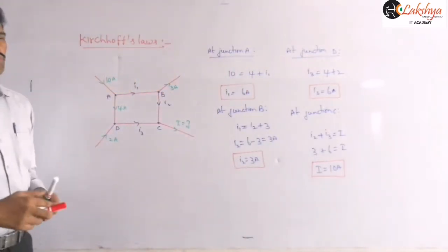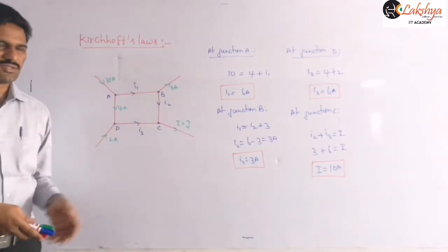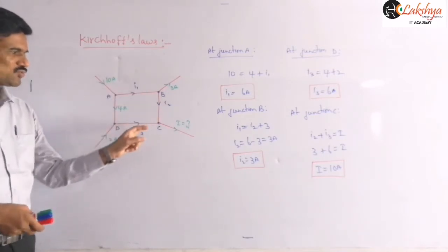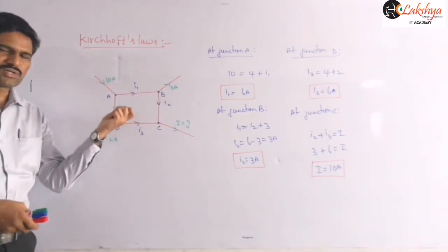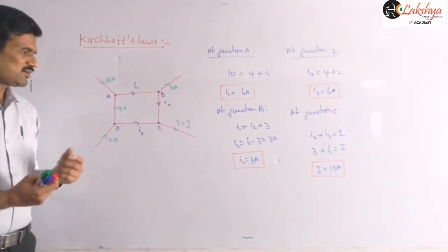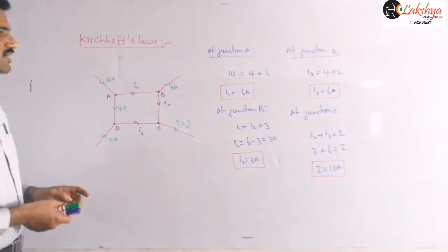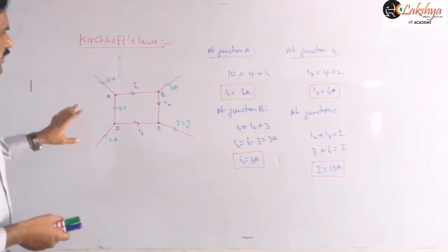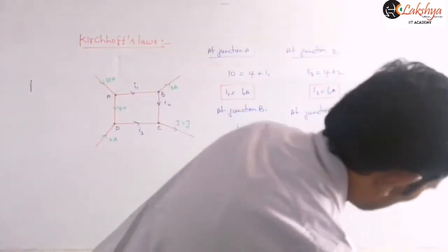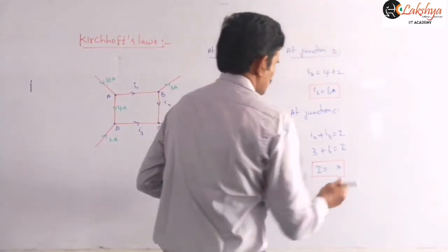And actually you can also say directly, this much lengthy calculation is not required, no need of writing the steps like this. Simply you can take this whole rectangle and consider it as one junction, right? Now directly you can apply the current flowing into the junction is equal to the current flowing out of the junction. Here the current flowing in is, sorry, this is 9. 6 plus 3, 9, sorry. It is 9 amperes.